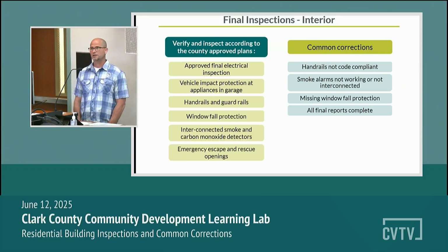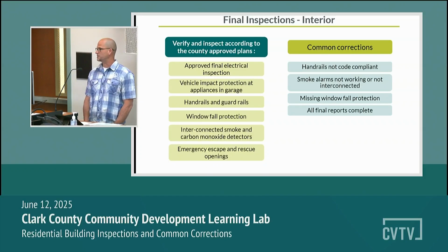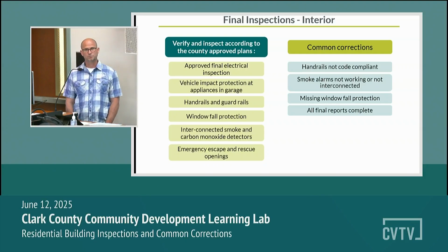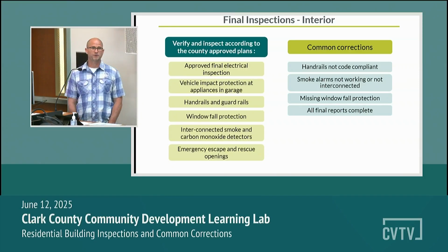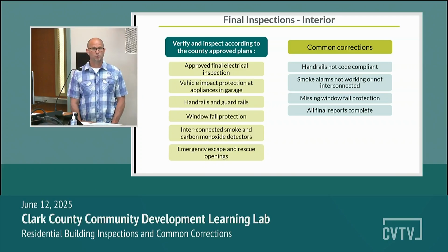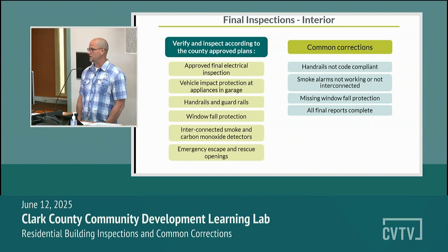So some items, like I said, we have quite a few corrections that we might have at handrails. So please reach out and talk about those if you're not familiar with them. Same with the smoke alarms. If they're not working, not interconnected, or you did an addition and the smoke alarms in the addition aren't working with the smoke alarms in the house, that's something that will have to be checked as well.